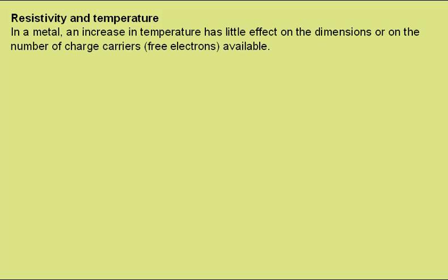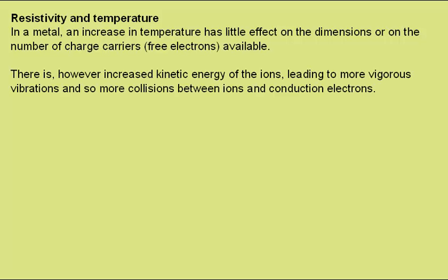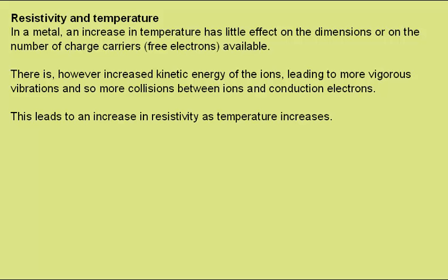Resistivity and temperature. In a metal, an increase in temperature has little effect on the dimensions or on the number of charge carriers or free electrons that are available. There is, however, increased kinetic energy of the ions within the metal, leading to more vigorous vibrations and so more collisions between the ions and the conduction electrons. This leads to an increase in resistivity as temperature increases.